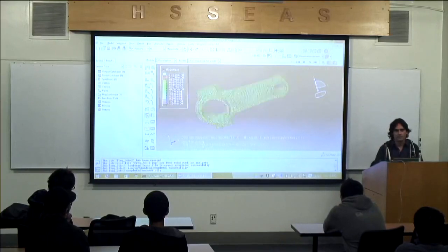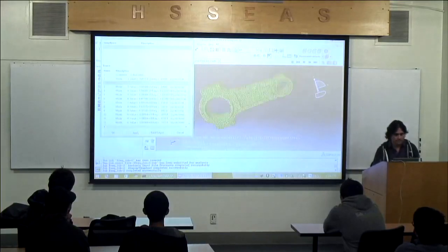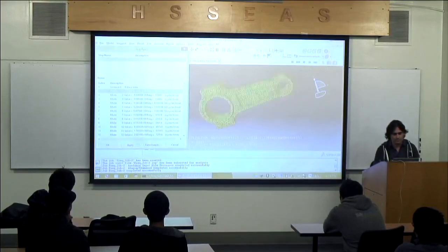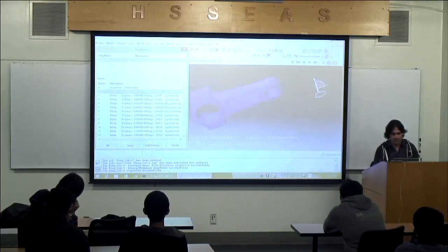You do result step frame. Go up where it says result step frame. Pull that up. It's literally easier to see than here. You can click any of them. You can see the first 6 are 0, basically. So 6 degrees of freedom. So by looking at the step frame, we can select any of the eigen frequencies, any of the mode shapes, and see what that is.